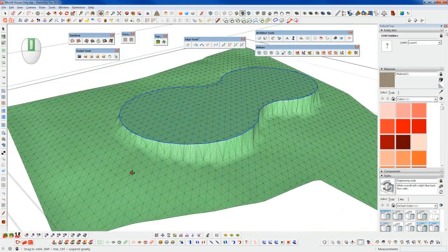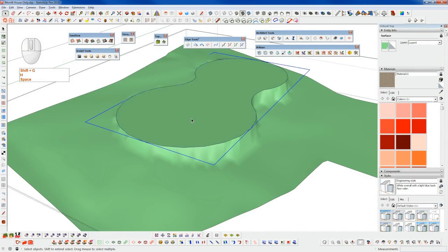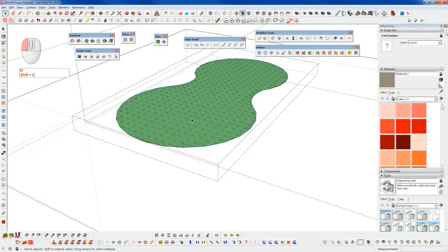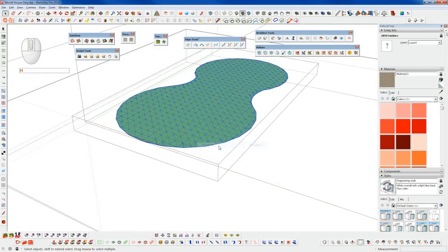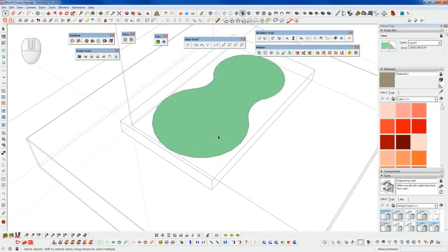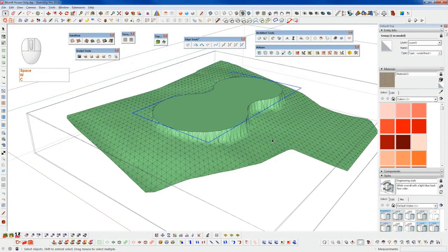And you can see if we maybe had a boulder wall or something going in around the outside, I can grab this center, group it, and I can even clean up here. And I'm going to run the plugin Fix-It 101, and that went through and got rid of all those coplanar edges. So now I just have a single surface here.